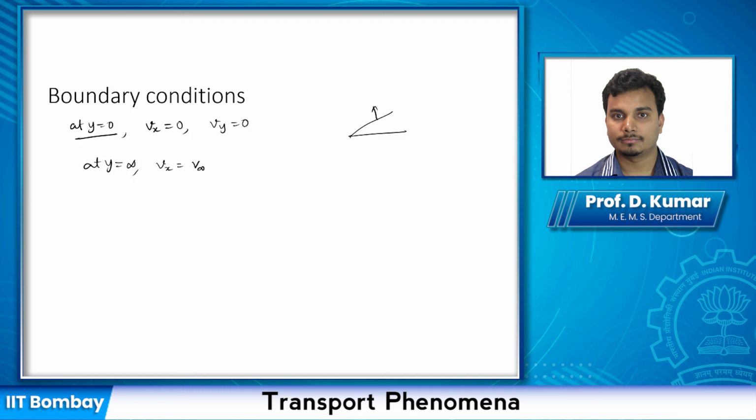Then you solve that third order ordinary differential equation using the method by Blasius. From there you can actually show that delta is equal to this. No, this is not velocity. This is kinematic viscosity times x by V infinity.